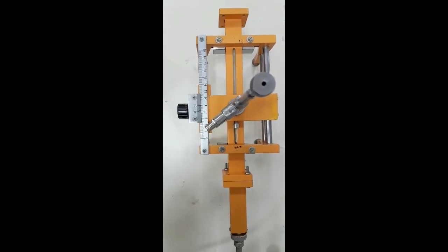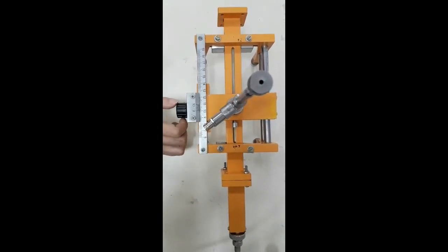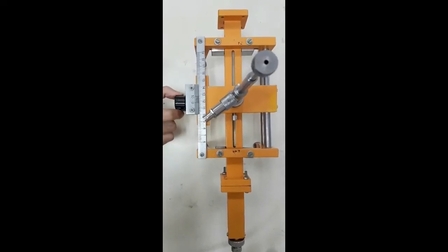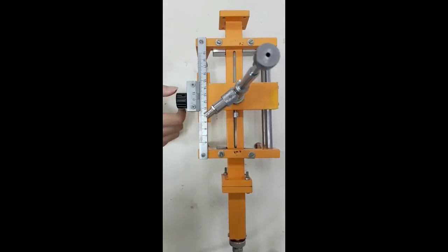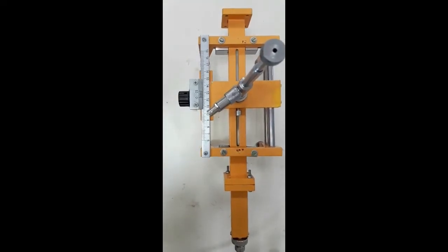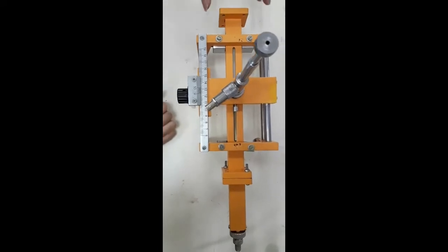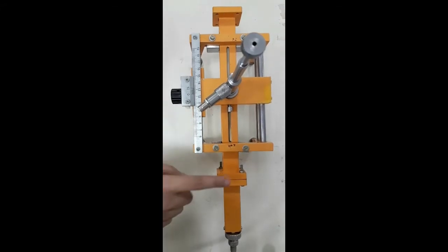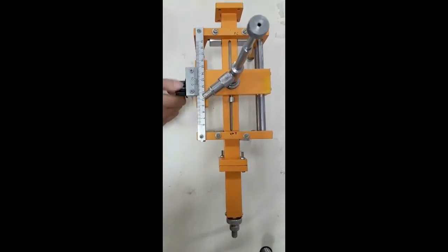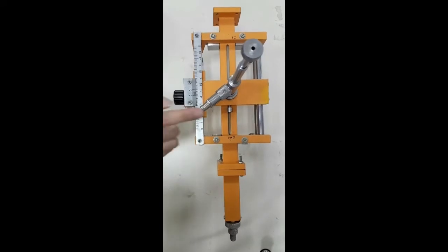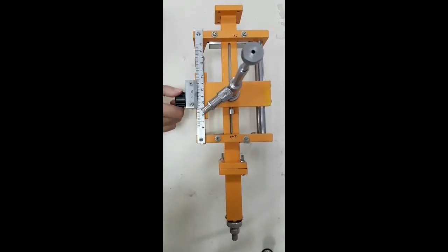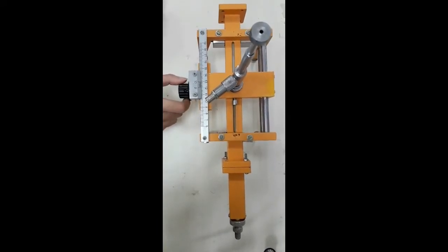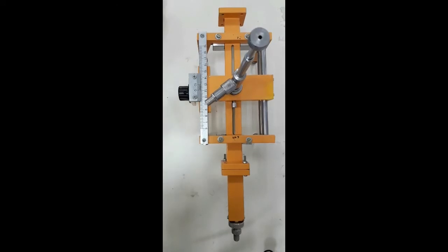Therefore, it can get an idea of the surface current or the fields that are generated inside. And you can see that the impedance characteristics, the maxima and minima, will repeat after every lambda by 4. So although we will not show this exact behavior right now, this is the place where you will connect the source and the load, over here on the other side. And this is using a voltage probe. You can connect an oscilloscope, you can connect a power detector, and by changing the position of this tunable movable probe, you can do a lot of measurements. So that we will do some other time.